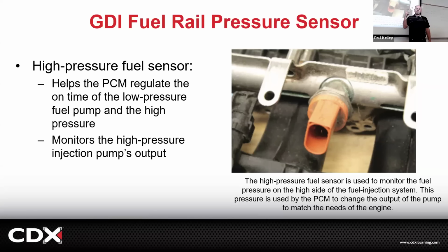you'd be like, let me check the mechanical pump. You might have to pop it off and see, like, is there any metal or wear or something? But if the cam looks good and the pump looks visually good, it's probably inside the pump. Would need a high pressure pump. Not a real hard diagnosis, to be honest, but they fail because they have an extremely hard job to do. Extremely hard. And the way we diagnose it's all really with a scan tool. So it's a decent system.